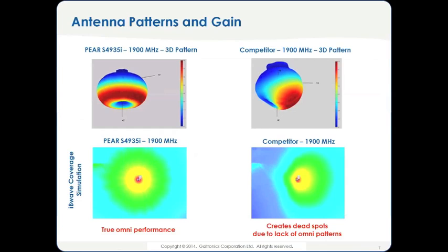It may be true that the other antenna has a higher gain, but based on the fundamentals that we just reviewed, we now know that higher gain means a preference for radiation in a given direction. If you're designing in-building applications where coverage is important, that preference for a given direction may not be what you're after.